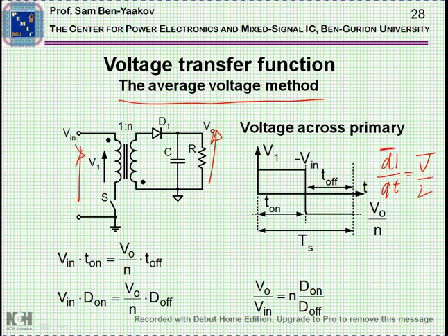This line stands for average, and this is average. So if the average voltage on the inductance is not 0, the average of i dt will not be 0, so the current will start climbing up or going down, and so this system will not be in a steady state. So if it is in steady state, this relationship must hold.